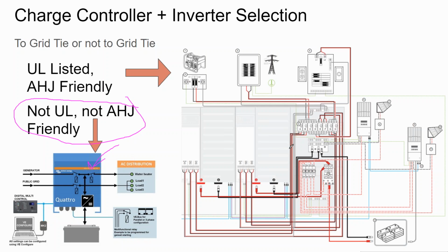That gets into kind of a downside of staying grid connected. I very much like this system. It's made by Schneider, whereas my cheap Chinese inverter that I also use pretty frequently is not stackable. You can't have them wired in parallel to each other.